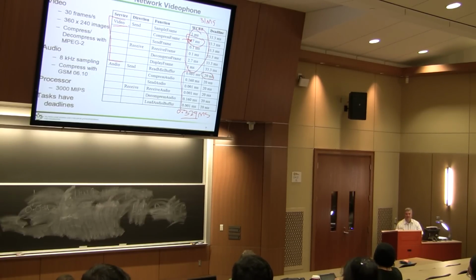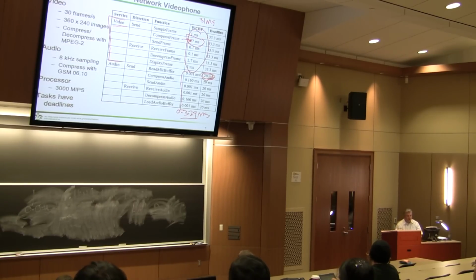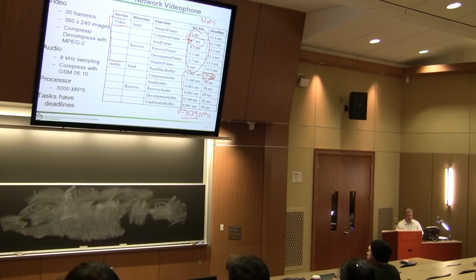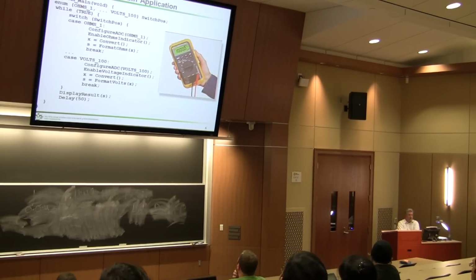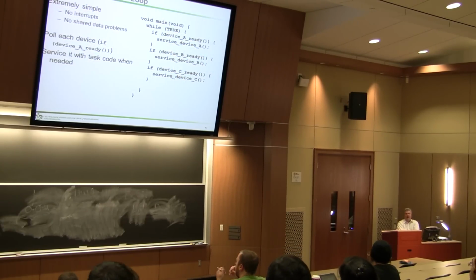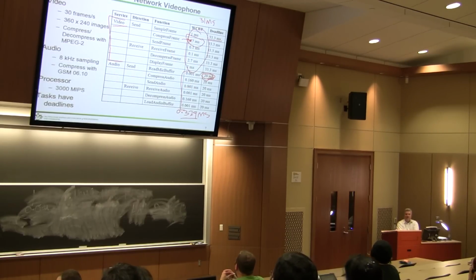Not really, right? Because even if we do 2 of these, remember, there's a possibility, since this happens every 20 milliseconds, even if we do 2 of these in this time frame, this is only going to be 0.65 milliseconds. Definitely an amount of time you'll be able to make this deadline without any problem at all. So maybe we need to think about whether this round-robin might not be the best application or best operating system for an application like this.